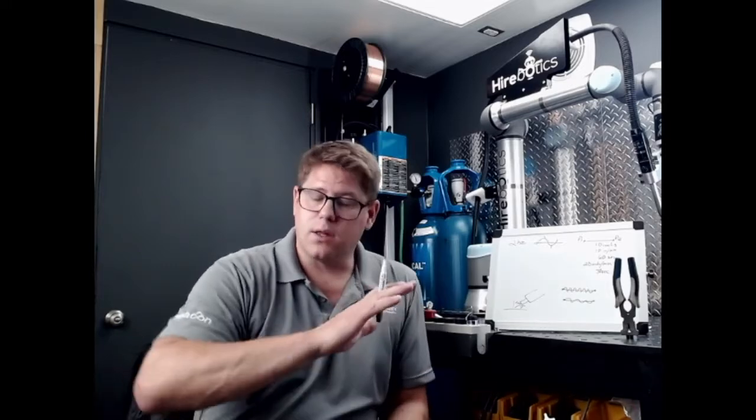You want to make sure that when you're watching that arc, the crater that's being carved out by the arc is being filled up with material as you're going across, nice and flat, and you get this beautiful looking weld when you're done. If all of a sudden you're getting scallopy top and bottom, it's not filling up, whatever, you either need to increase your frequency, you need to increase your wire and put more wire in, or you need to slow down. One of those 3 things, based upon the theory of this, to get that weld to wash out.